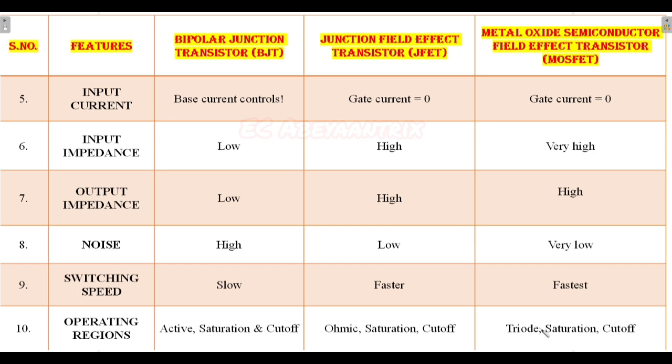The Shockley diode equation. You remember that equation? We have learned Shockley diode equation in 3 different videos. In PN junction diode also, we have discussed Shockley diode equation. In that, we have learned the Shockley diode equation as I equal to Is into e power V by eta Vt minus 1. I have discussed in PN junction video. You can refer that. Okay, so similarly for a JFET also there is a Shockley equation.